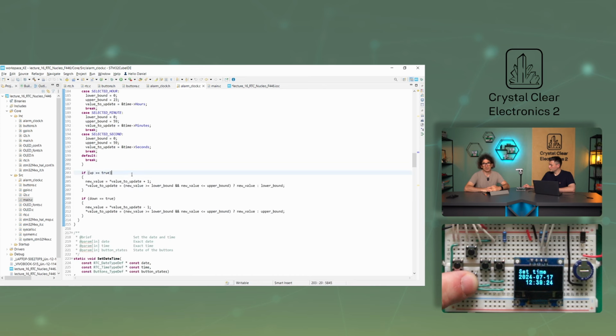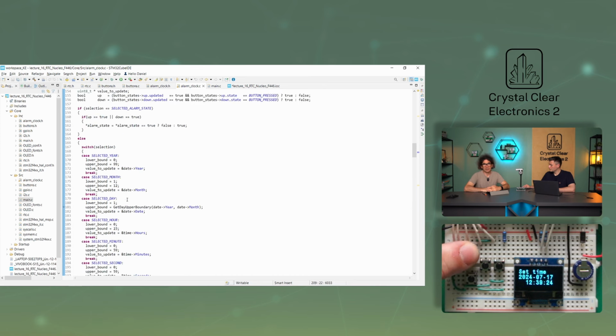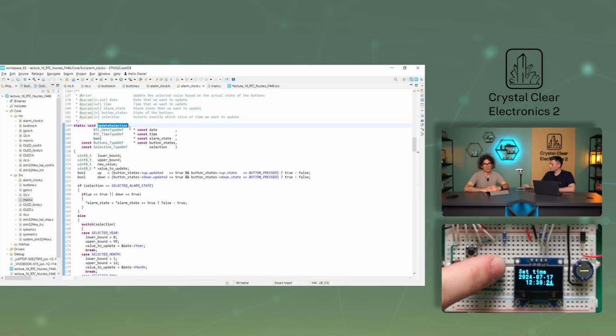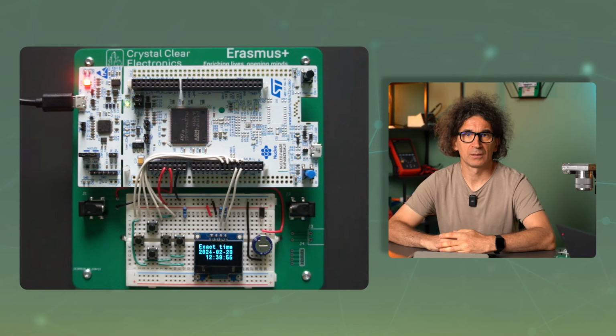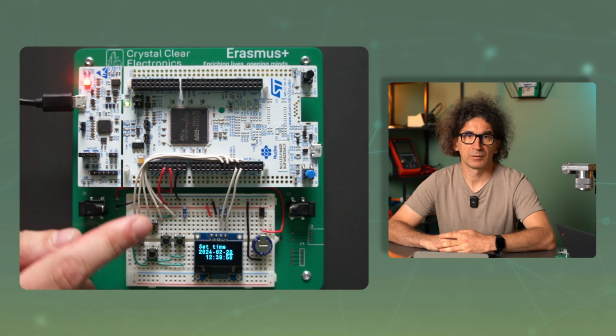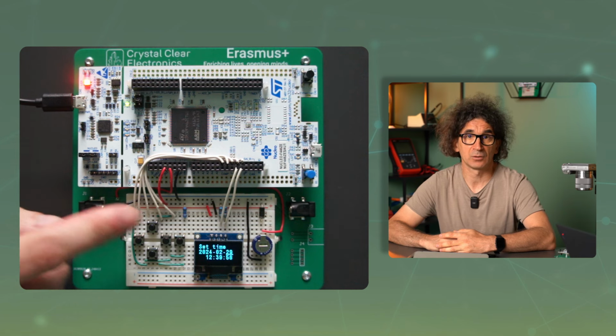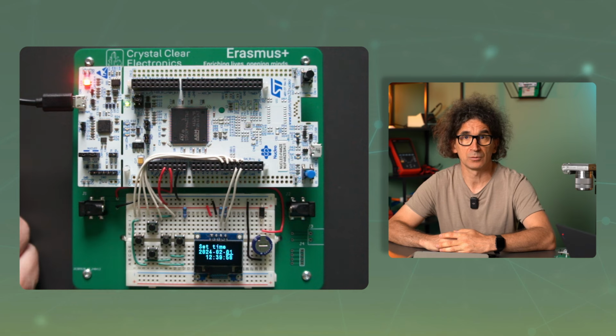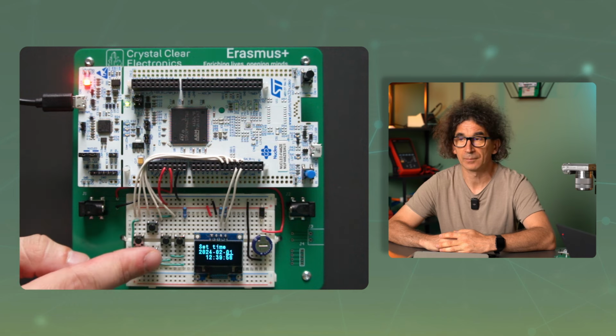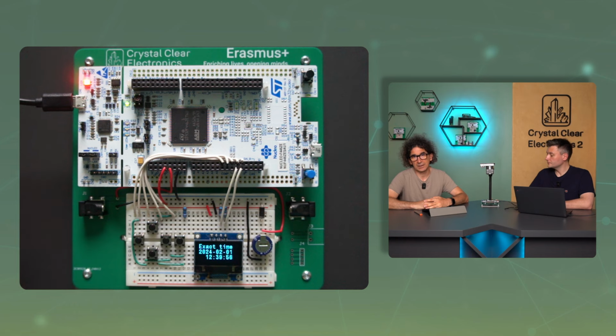Toggles and value limits are controlled by the updateSelection helper function. Suppose it is a leap year, the set month is February, the days are currently selected, and the value is 28. Pressing an up key will let updateSelection set the value to 29, and pressing up again will flip the value from 29 to 1. Pressing the enter button will exit the set clock and date state, performing the actions associated with D2.